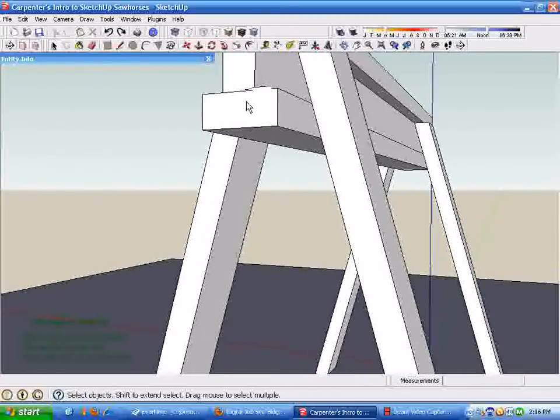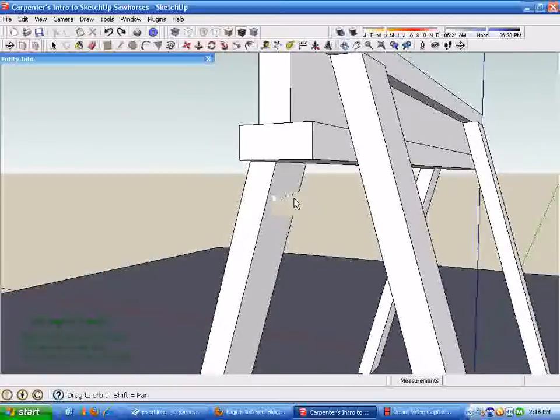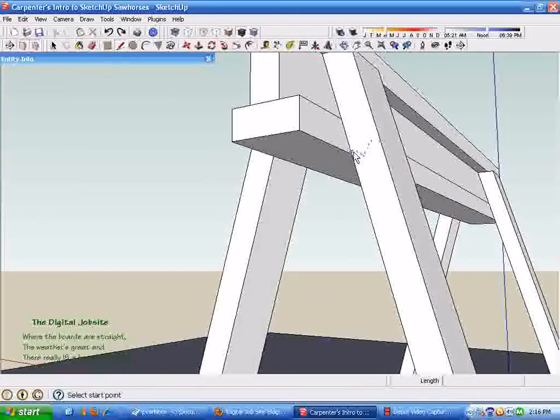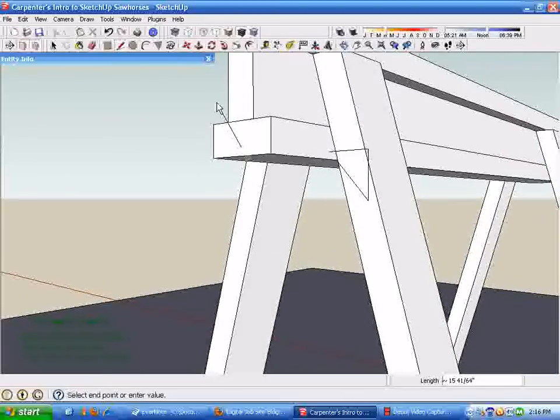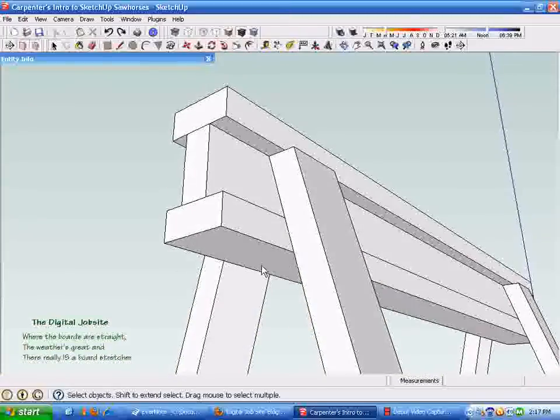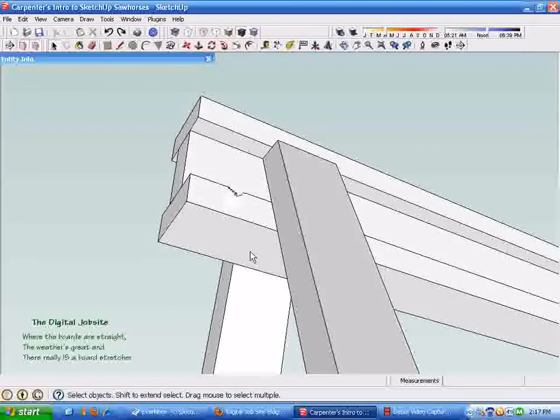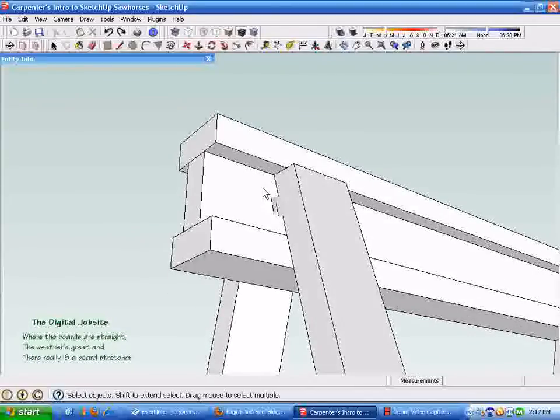And let's say we want to make the gusset 6 inches tall and then to fit underneath here. If we try to draw something 6 inches tall and we want it to be kind of on this line, it's going to be kind of tricky to get everything to fit where we want it. And there's ways of doing this, but I want to introduce guidelines here. It's kind of like using your pencil in a square. If you had a Swanson square, you could slide it up next to these horses and get a line on the bottom of that horse where this plywood's going to act, but we don't have that here.